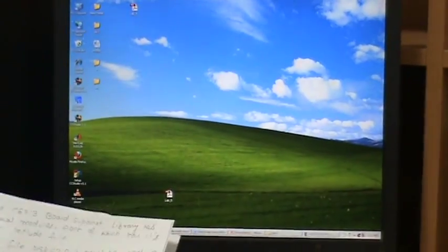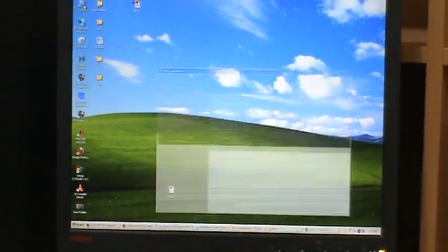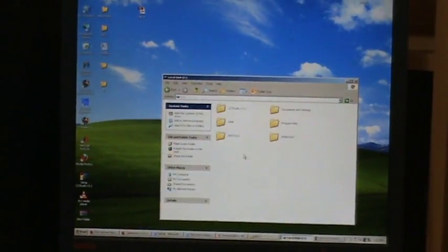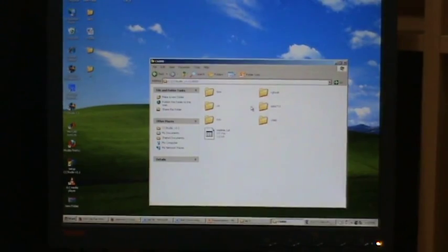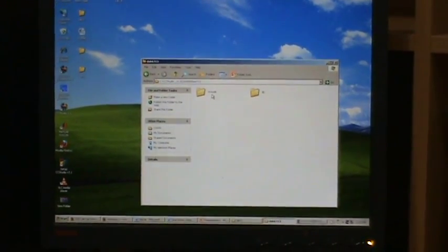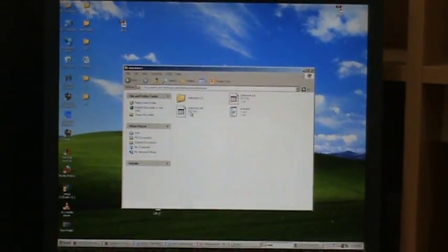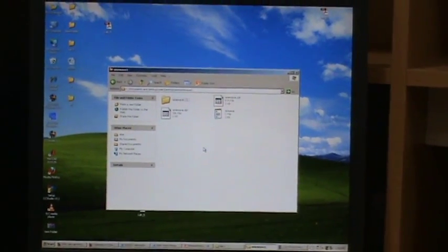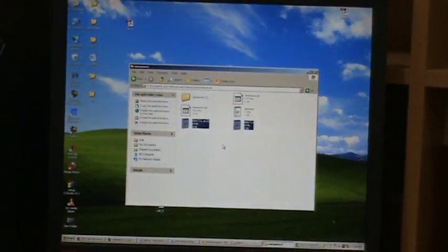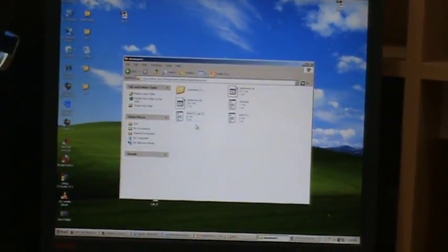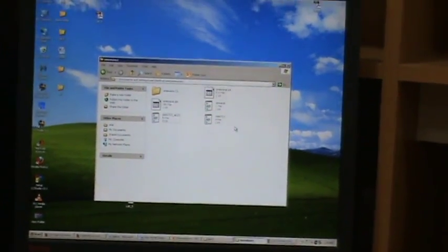Another thing, we have to include 2 header files. So again, go to my computer, local disk C, CCS Studio, C6000, DSK 6713, include this folder. We have to copy these files: one is the AIC codec file, another one is the header file.